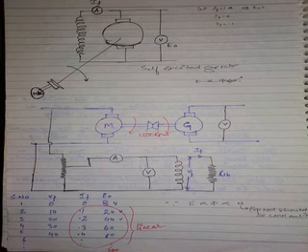Where is point P now? Is it the same value? Is it reduced or is it decreased? It is reduced. The maximum limit, the maximum voltage the machine can build up has decreased to some value. Now let us say the field resistance is increased to 200 ohms. Definitely the line will go up. So let us say this point now.